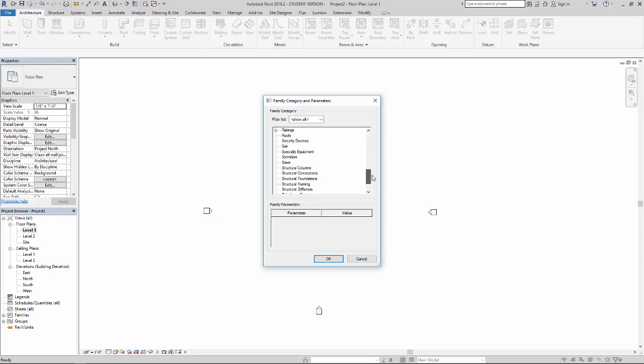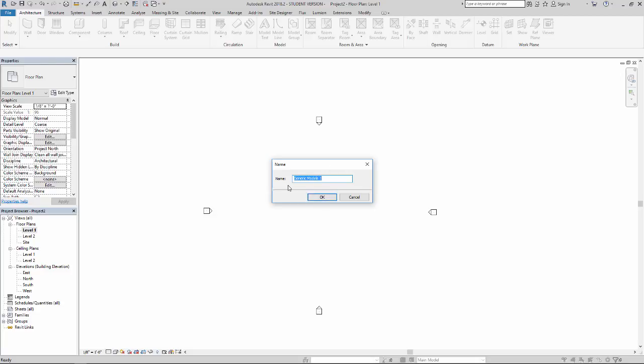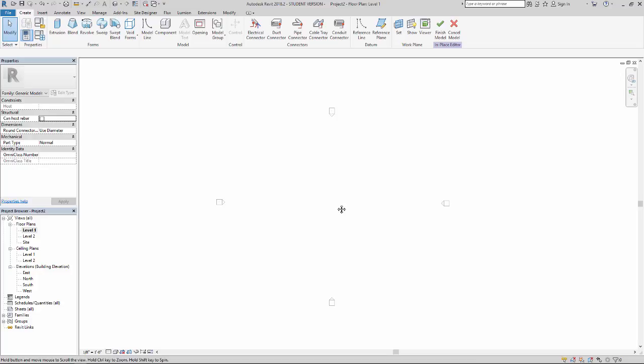As you get fairly advanced in Revit, you can certainly start assigning your custom components specific types of families to reside within. However, as you're learning Revit, I typically recommend sticking with one of the two, either generic models or massing models. Now, the massing model is going to open up a more advanced set of tools. So again, first couple of passes, we're going to work with the generic model family for custom components. So I'm going to highlight generic models and select OK. And I'm not going to worry too much about the name. I'm just going to say OK to that as well.